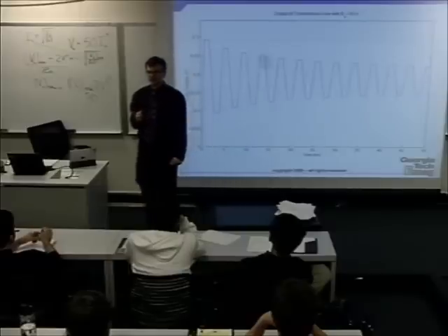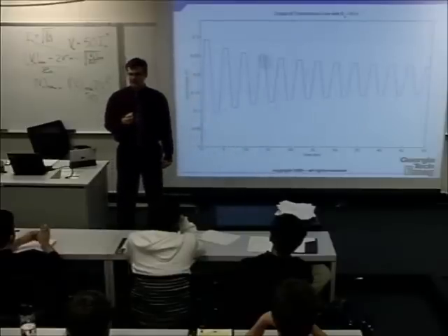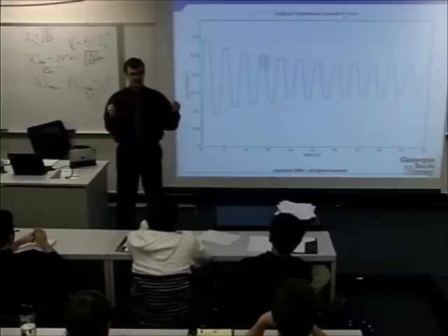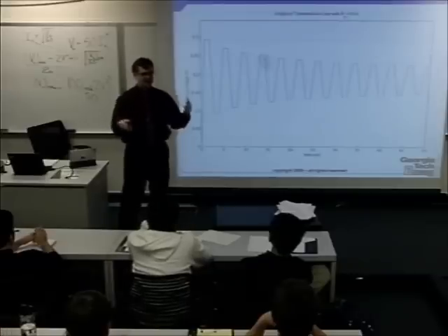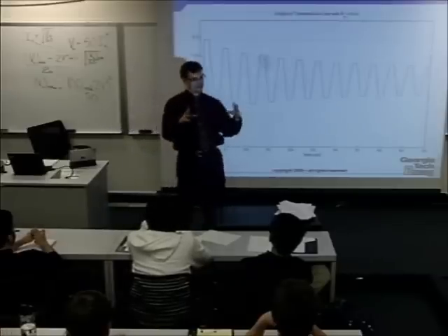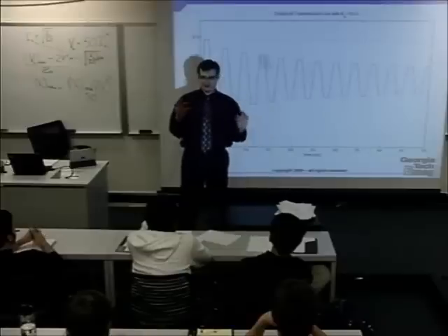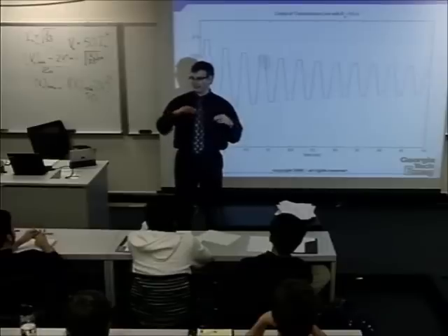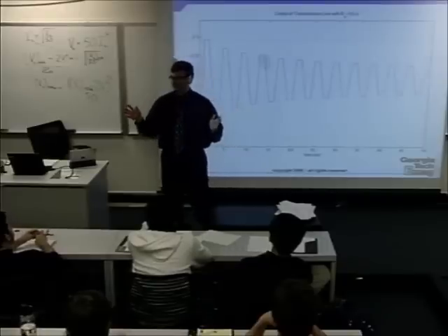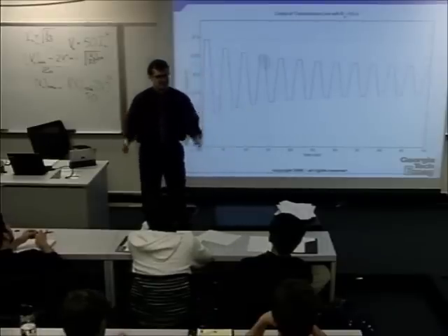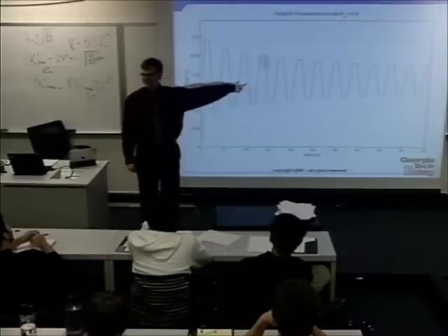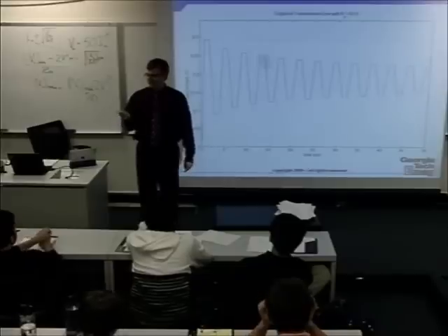What's going to determine the period of the oscillator? It's basically how long that transmission line is. So if you can control the geometry of your transmission line and you make it out of materials that don't have a big thermal expansion coefficient, you can very precisely tune your oscillator and it'll be stable. And it'll operate literally in the gigahertz or millimeter waves. But it violates everything that we've learned about these circuits in this class. There is no steady state, even though it's only connected to DC. And that's typical of nonlinear circuits.